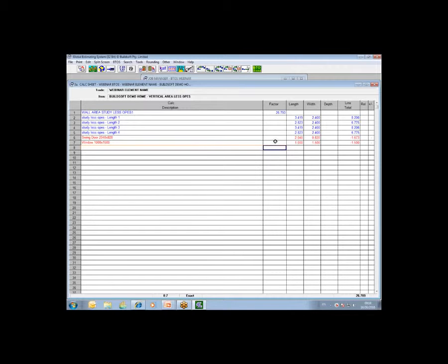that you'd applied. Now, if there was a case of the same opening being applied a number of times through the drawing, you would get a factor applied here, 2 times. There's two doors of the same size, or 3 windows of the same size with the factor of 3 in there as well. So that is, again, how deductions are applied.